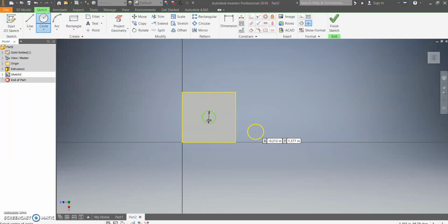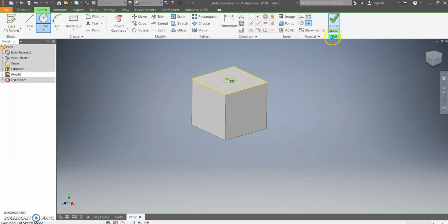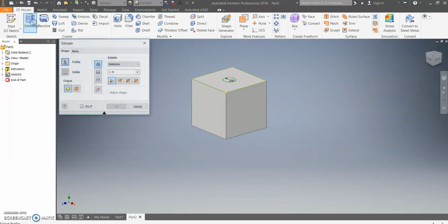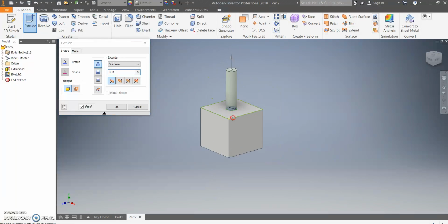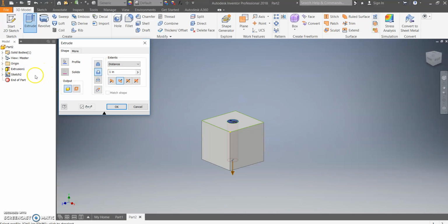So I want to make that a three-dimensional command. Once again, I'll say Finish Sketch, and I'll extrude. I'll choose my drawing. Before, we added to it; now we're going to subtract. So rather than saying add, we're going to cut a hole through the center. I can't choose the add direction, because that would basically be adding. So we want to subtract.